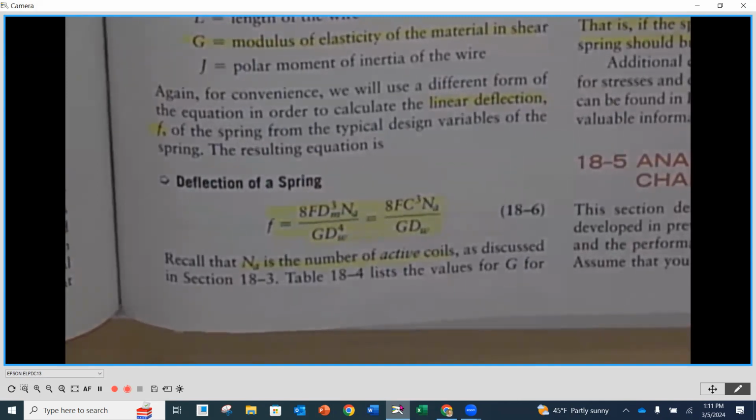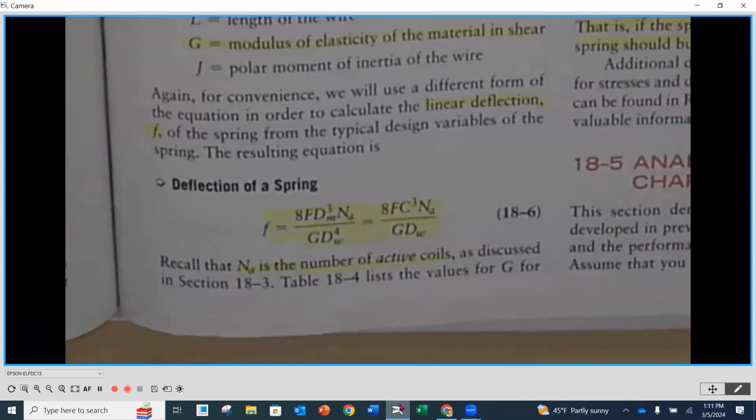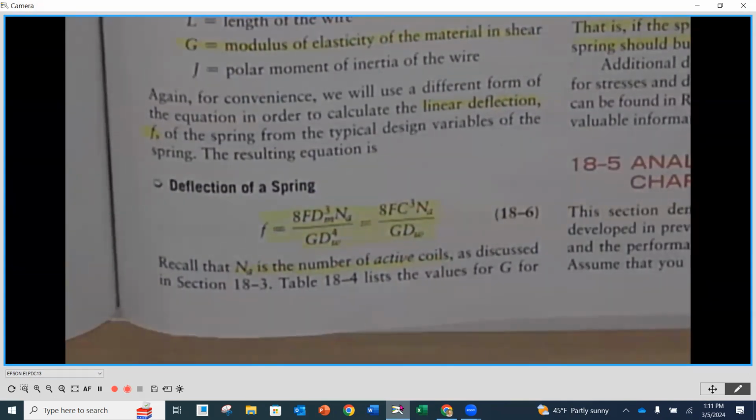There was modulus of elasticity, and then there was shear modulus. Modulus of elasticity was when we pulled on a specimen in tension, and we wanted to know what was the slope of the line in that elastic limit, right? That was the modulus of elasticity, capital E, and that was based on a tensile test.